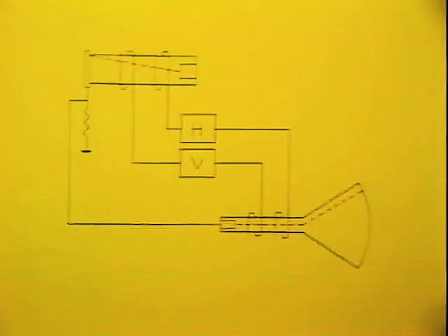The horizontal coils produce the left to right scan of the beam and then the fast retrace. The vertical coils produce the slow downward movement of the beam until it reaches the bottom, and then the faster vertical retrace to the top. The combined effect of the two coils is to move the beam in a continual horizontal scanning pattern and to make each successive line appear under the previous one. When the screen has been completely covered, the beam returns to the top and starts all over again. The nature of the electric signals fed to the coils will now be covered.